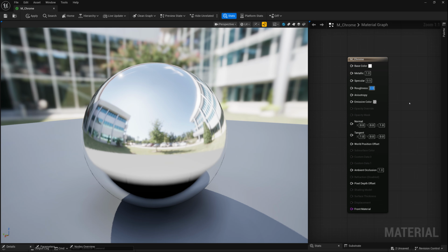If we want to add roughness, we could add a normal map to break up the surface. We could add a bump map. We could add displacement, or even model the surface to have more breaks and dips in it. But the roughness control allows us to define how smooth or rough the surface is at a very, very fine level, down to the micro facets of that surface.